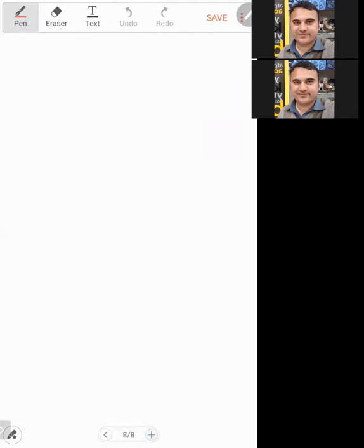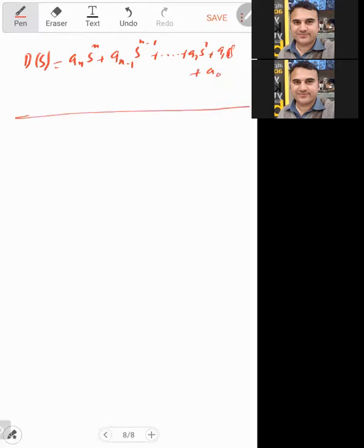Let me write again the denominator polynomial D(s) equal to a_n s^n + a_(n-1) s^(n-1) + ... + a_2 s^2 + a_1 s + a_0. And then we make the table. The table is what? You have s^n and s^(n-1).